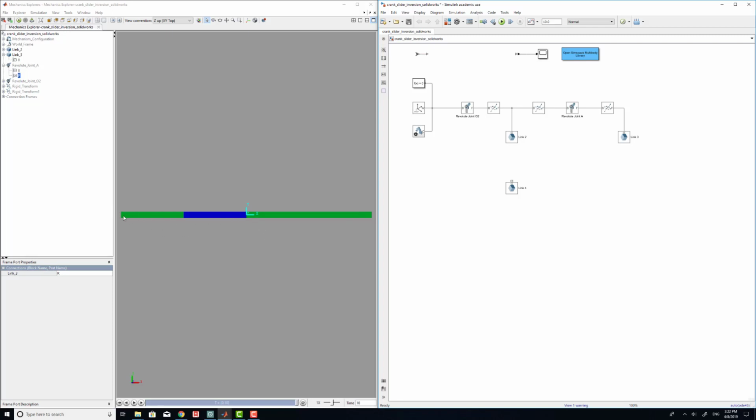In this case, the right position for your green bar is the edge of the link. So we need to move the green bar such that the edge of the link overlaps with your follower. And that's why we need to move everything along the x positive direction by half of the length. Okay, so we can click run, and you see everything is connected correctly.